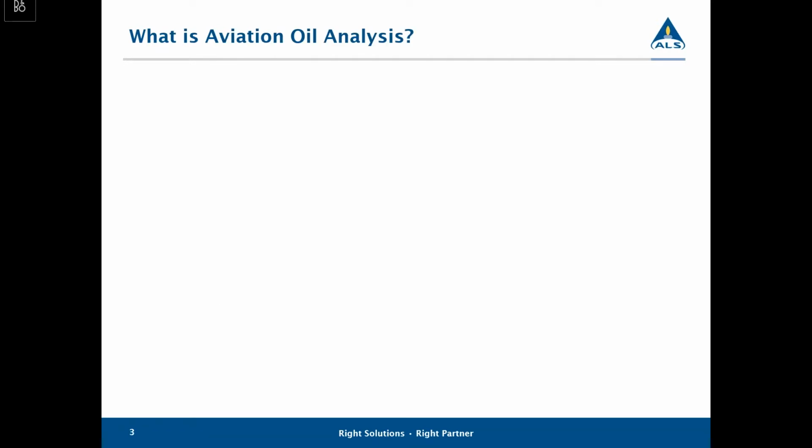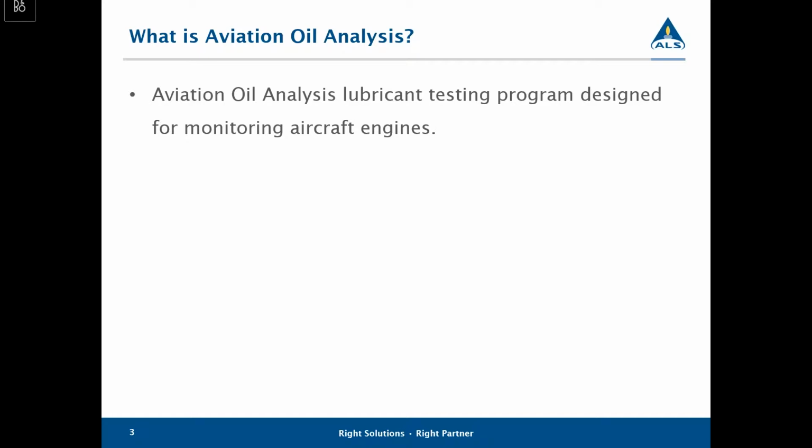So what is aviation oil analysis? Many people that I talk to in my travels, when they ask what I do and I bring up oil analysis, I have to then further explain what we do. There are many out there for whom oil analysis is a foreign concept. I use the analogy that it's kind of like getting your blood tested. We go to our doctor, we want to make sure our health is good. I use that as an analogy for the industrial and mechanical side of the world: we do the same thing. We take lubricants, which are the lifeblood of those systems, and we test and try to diagnose and improve maintenance practices. So aviation oil analysis in and of itself is a testing program designed for monitoring aircraft engines.